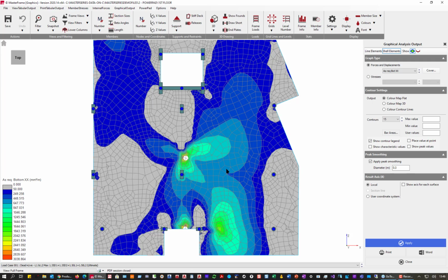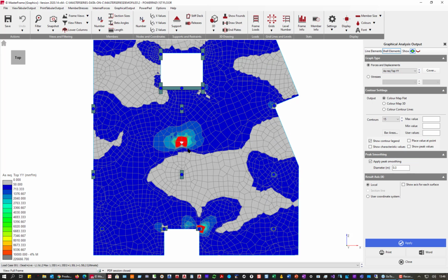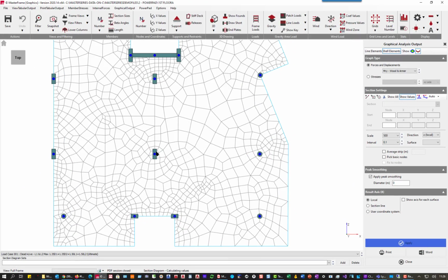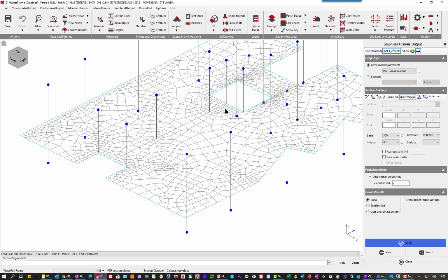So this slab itself may need to be thickened, or we may need to go for heavier reinforcement in these areas. When we get to the top steel, obviously that's going to be a lot less displayed, and we'll see that, it's saying around these we're needing drastic amounts, but we can spread that out. What we want to do is to take a line down through this part of the slab, but before I do that I'm just going to rotate it into isometric view, otherwise we could have been clicking on the top nodes rather than the physical nodes.